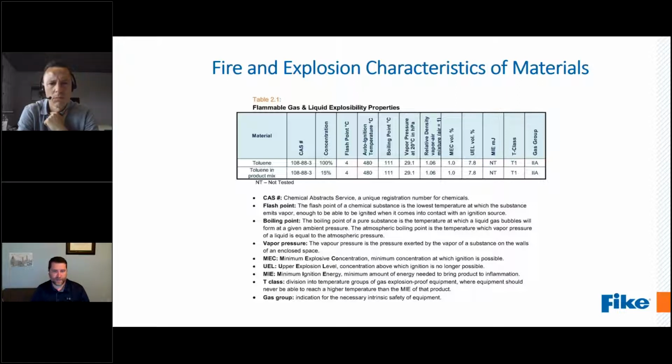You've got the MEC, minimal explosible concentration, or you might see this reported as LEL, the lower explosion limit or level. That's the minimum concentration at which ignition is possible. And then you've got the UEL, the upper explosion level, the concentration above which ignition is no longer possible. So in this case, that gives us the range of what volume percent in air that